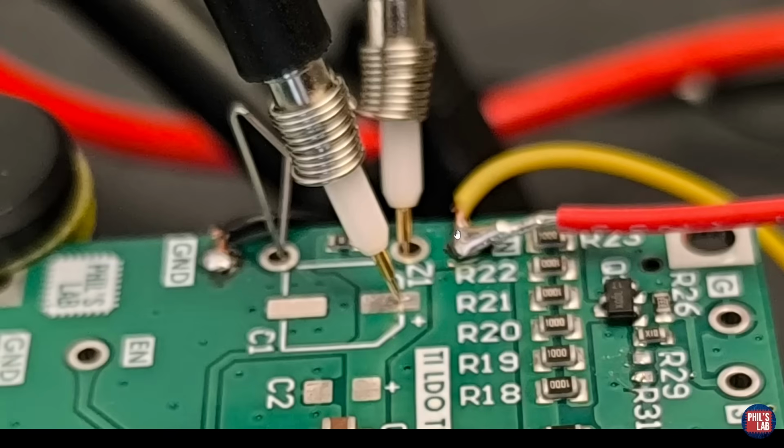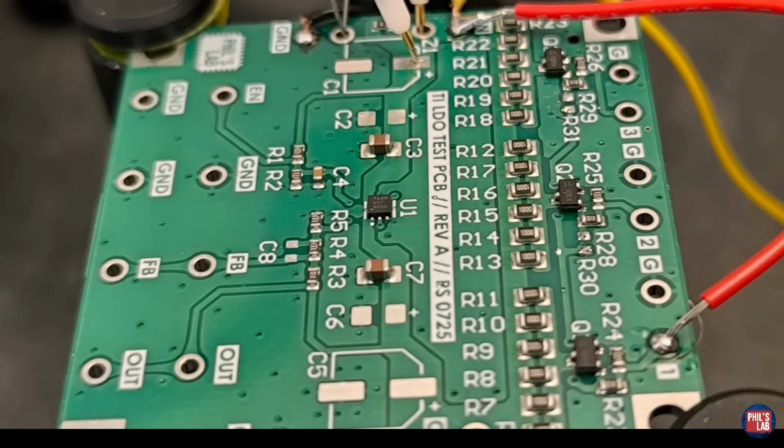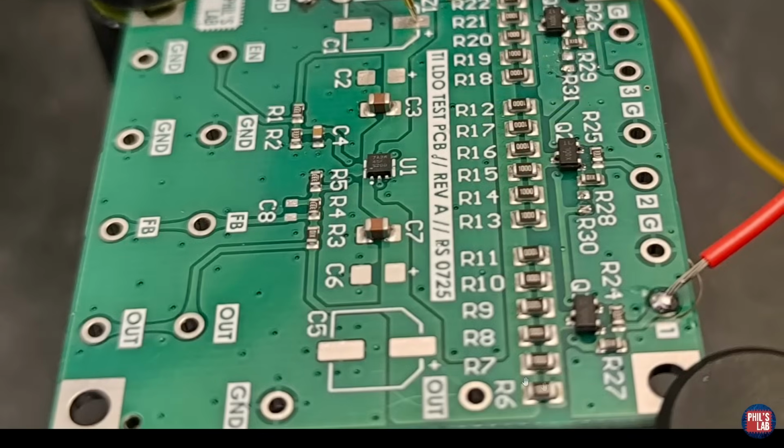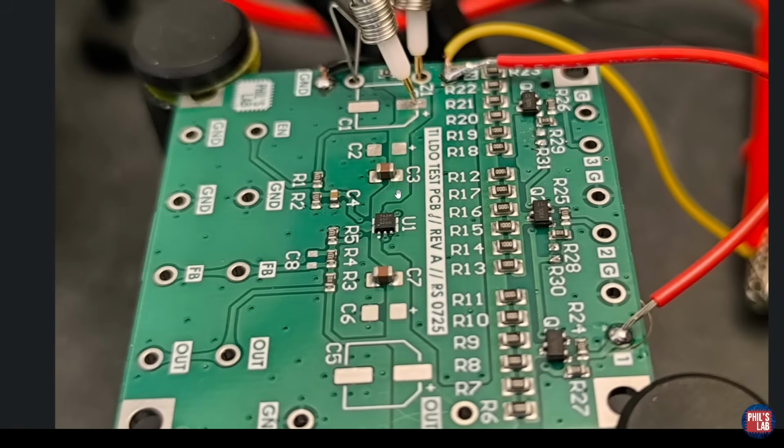The DC input terminals to this LDO test board are taken, of course, from the line injector output. Keep in mind this image still shows C3 in place, but I actually have removed the input capacitor C3 for reasons that I'll share in just a bit. And I've also enabled my first MOSFET here with this resistor array bank, so this gives me 150 milliamp output sink current directly at the output. So this is our calibration test setup for now.